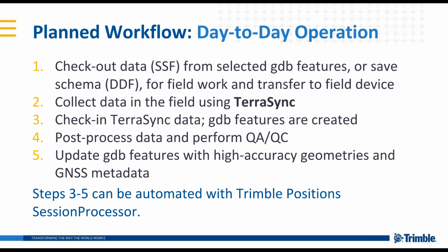If you're interested in new data collection only, you would take that DDF out to the field and transfer it to your field device, collect data using TerraSync, and when you come back, you would take that SSF that you collected, get it onto your desktop, and do a check-in. You would automatically create the geodatabase features, and you'd have your session to work with where you could post-process it, do QA/QC, and then when you're done, update your geodatabase features, and this is just clicking a button, update your geodatabase features with high accuracy geometries and metadata.